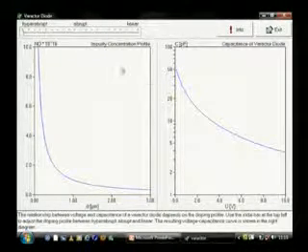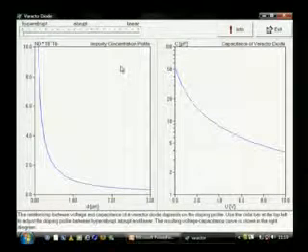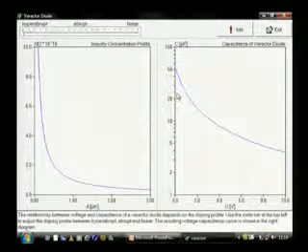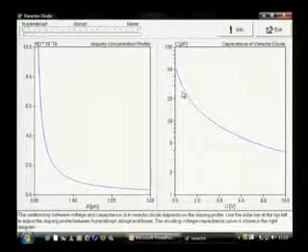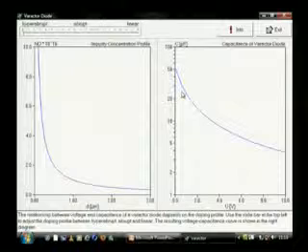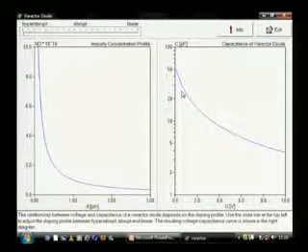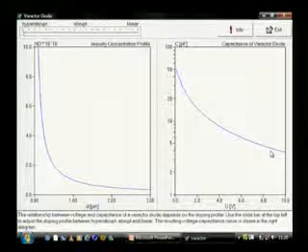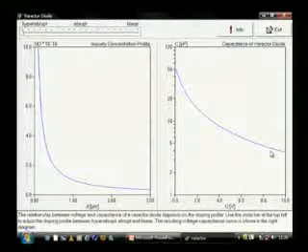Now what is the use of this capacitance? If we increase the doping into the PN junction diode, the capacitance increases enormously. So at a constant doping profile, if we change the reverse bias voltage, we can have a change in the capacitance by only providing the voltage. We don't have to put n number of capacitors in our circuits.